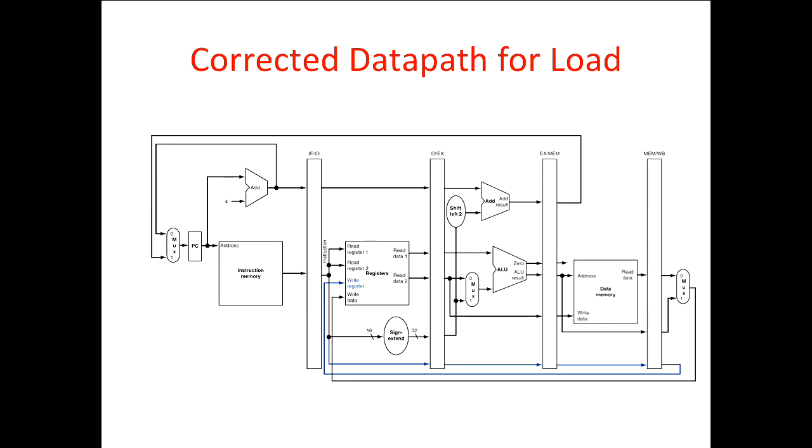So remember when we talked about decoding the control signals last lecture, there's a table of, if these bits are in the instruction, this means it's a load, and a load you can decode to mean it writes the register using the address in the RT field. So all that logic, you kind of replicate in each pipe stage. But notice you only need in each pipe stage the control decode for the stuff that happens in that pipe stage. So at the end, you just need to know: am I writing a register? And if I'm writing a register, which register is it?